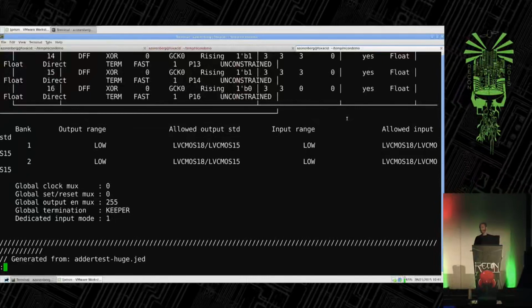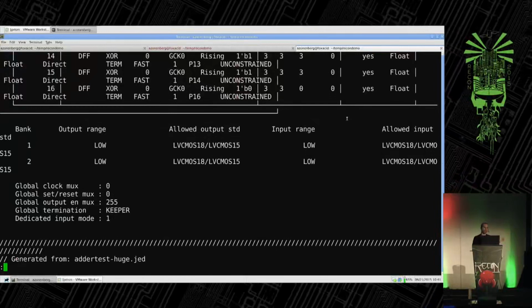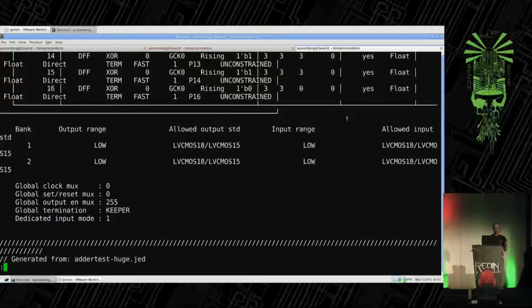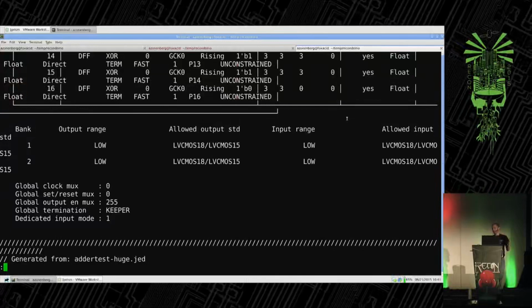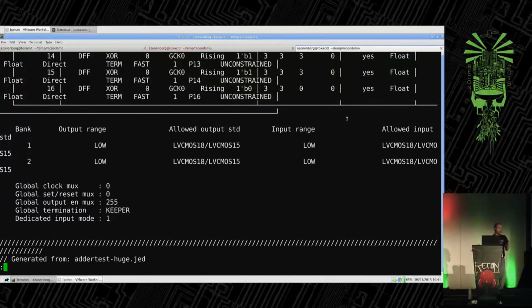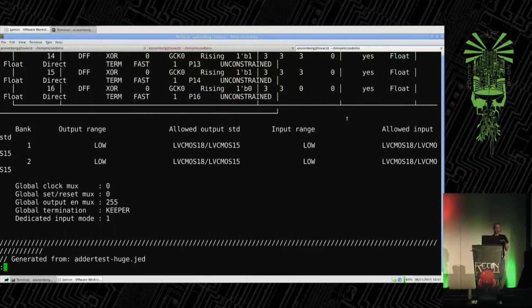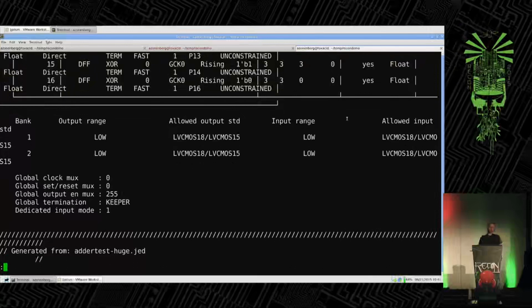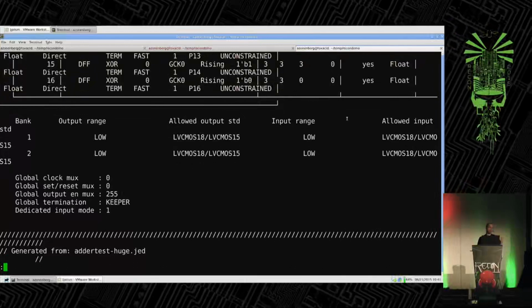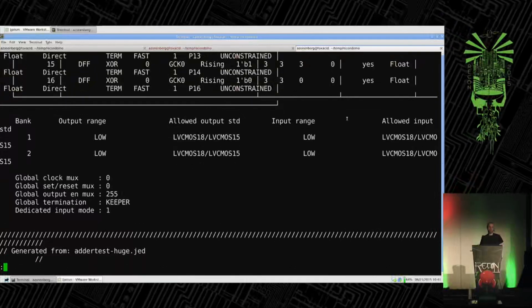So my guess is what this does internally. I have not fully reverse engineered all of the I/O driver circuitry, but what I'm pretty sure it does is it selects a single threshold or another, and then thicker or thinner gate oxide in the output. There's about 4 or 5 different sets of drivers in the output for fast and slow, different voltages, and so on. I haven't actually done TEM cross sections and measured the transistors or anything like that. It wasn't necessary for this.